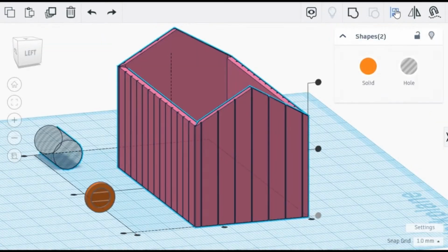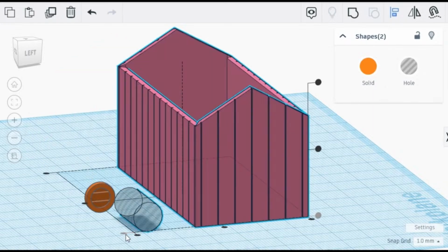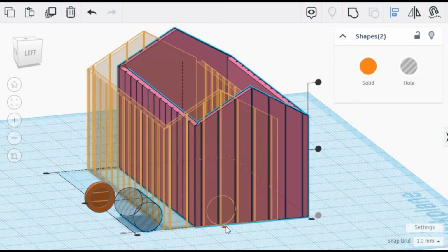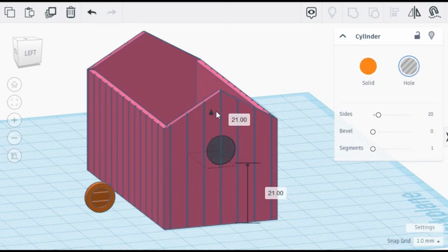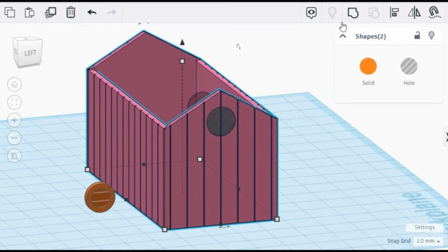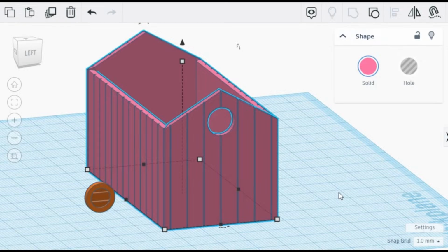Alternately, I use Tinkercad to create a hole the same size as the louver but deeper, and then position the hole as a punch into the side of a wall prior to inserting a separately printed louver. This technique has the advantage of allowing you to create the louver in a different color than the wall without tedious painting.